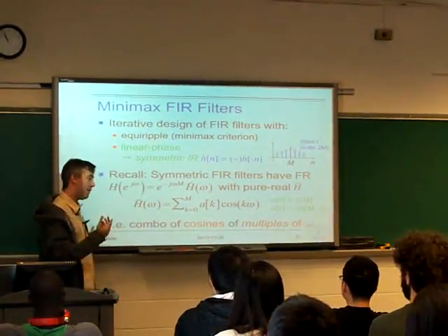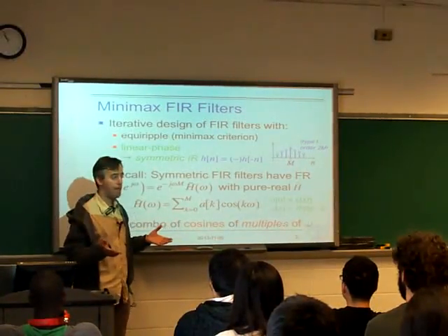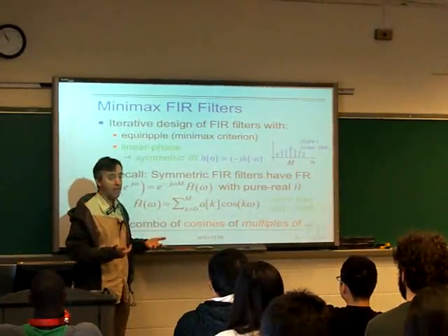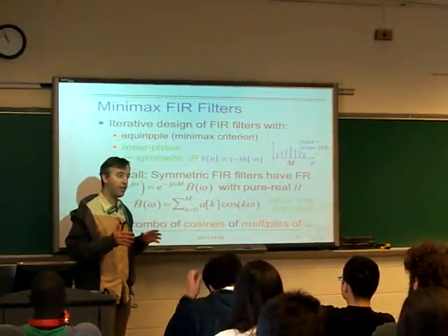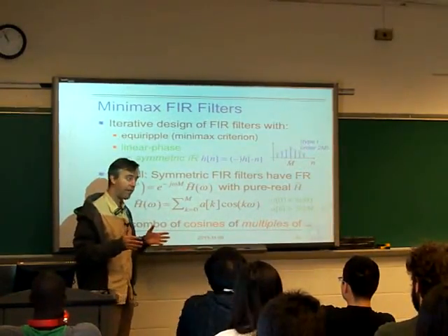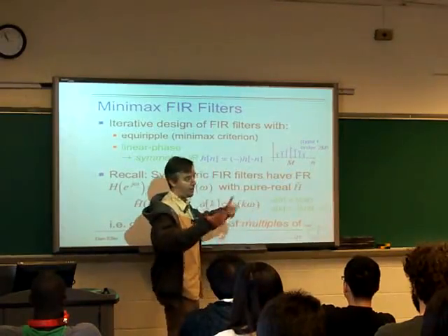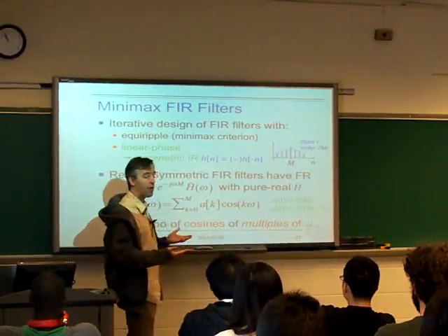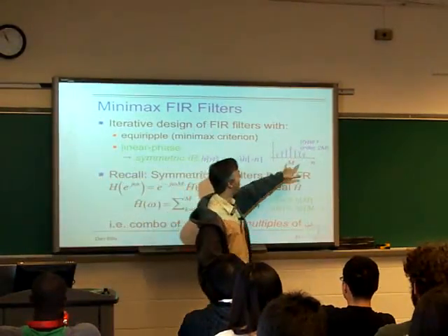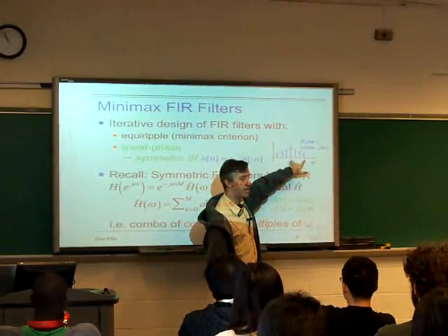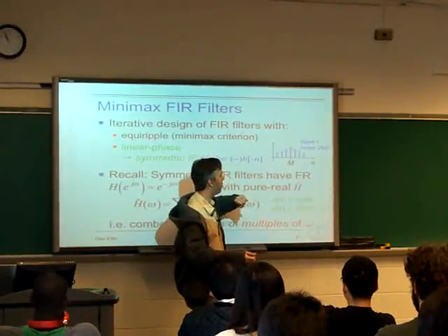In theory, we could let the phase response do whatever it wants to do. But we can also specify that as a constraint. So we can say, okay, we're searching within the space of linear phase FIR filters, that is filters with symmetric impulse responses, and we can write that into our optimization routine by only having now these m independent values giving us a 2m minus 1 point filter or something like that.